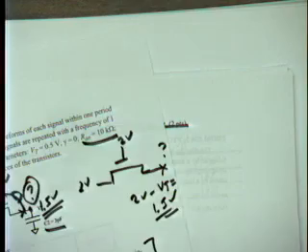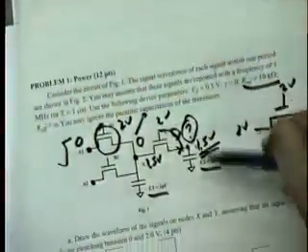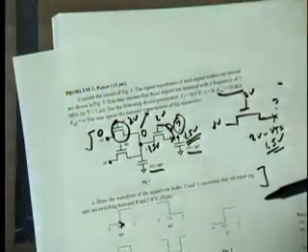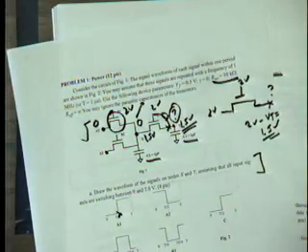I'm not too worried about this for this exam because dynamic power dissipation is something we are, well, you should know about CL VDD squared, but we're not going to discuss the dynamic power dissipation of an inverter as part of the material for this midterm. But what you would do in this case is you look at every node in the network, node X and Y, and you figure out how often do they basically change from 0 to high voltage.